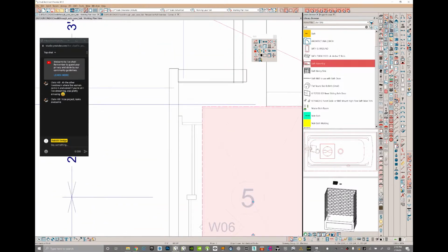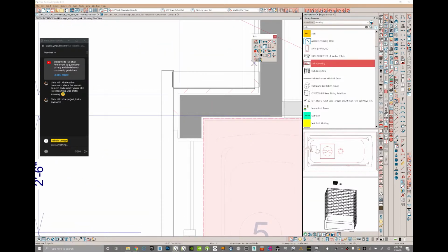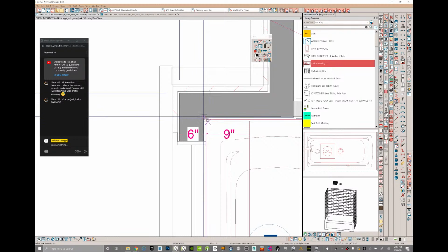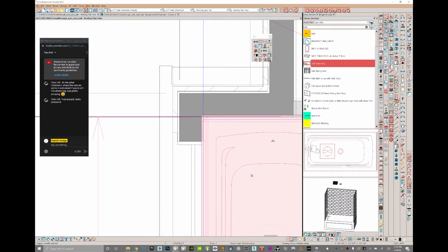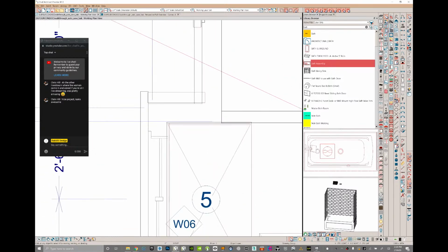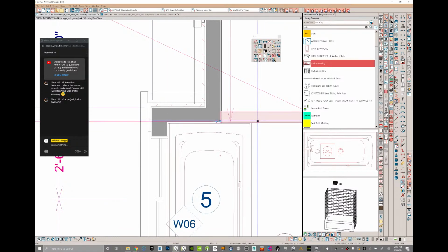And in fact, this particular symbol needs to be butt to framing. So let's unblock it. It's going to keep everything selected. And then let's do a point to point on this inside edge. Oops, I did a little too much actually. And looks like we've got another wall alignment issue. This is not lining up with the exterior wall, so let's get that lined up.